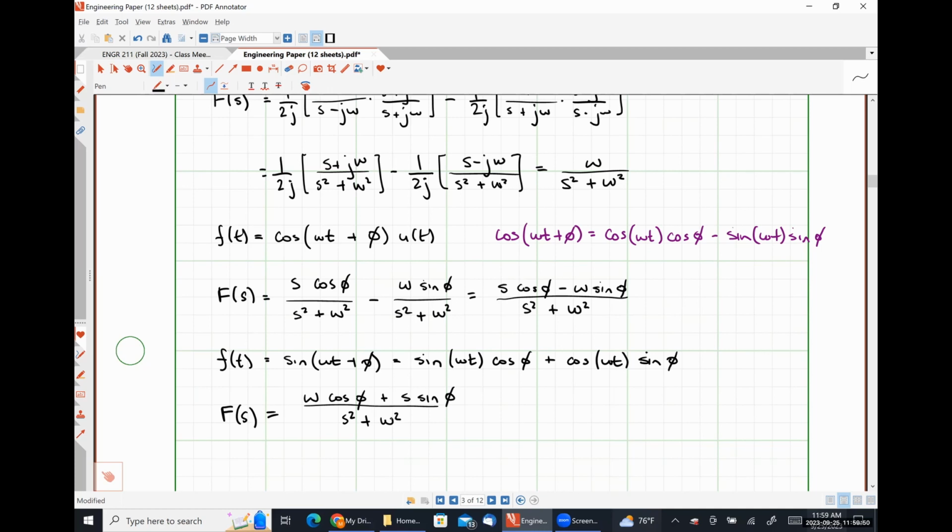Absolutely. That is involved in the ideal transformer stuff. No. Why do you need one? A is equal to N2 over N1. When you refer impedances from the secondary to the primary, you divide by A squared. When you refer them from the primary to the secondary, you multiply by A squared.